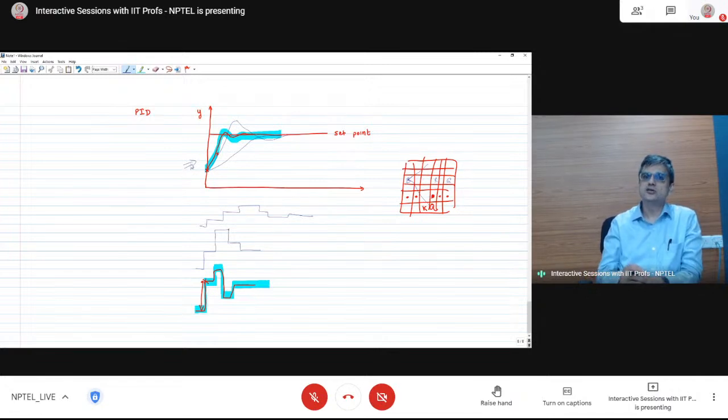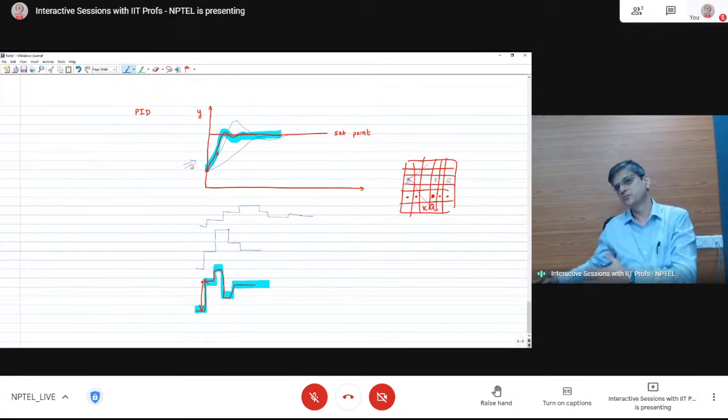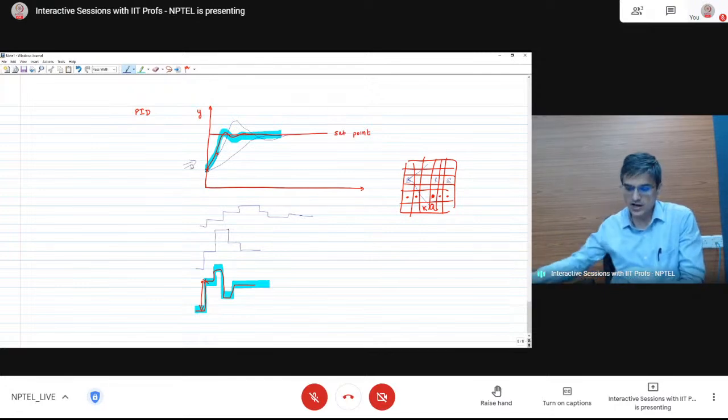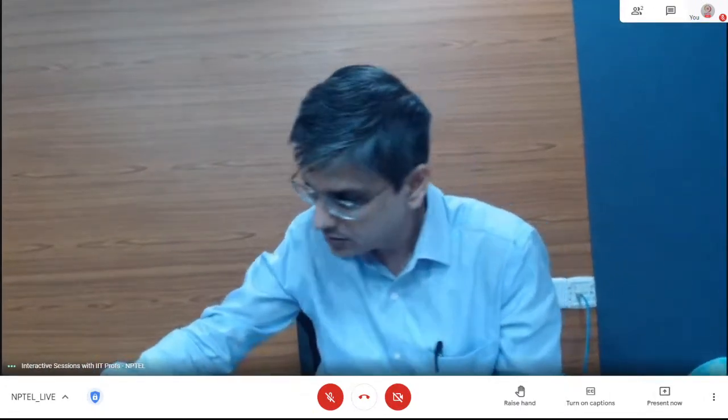If you are used to the concept of optimization, then MPC is much more related to optimization. The simple question that MPC asks is: what is the best set of control moves into the future, found by solving an optimization problem subject to the current information that we have? The current information comes from a controller. The optimization problem is solved by the optimizer. If you don't have the optimization background, then please skip what I just explained in the last half minute.